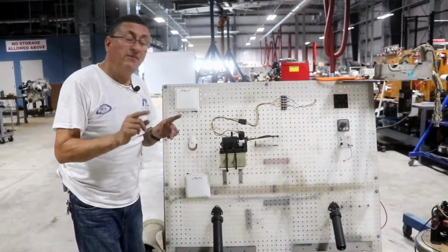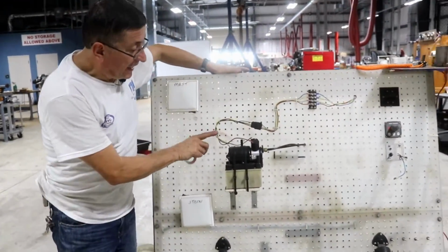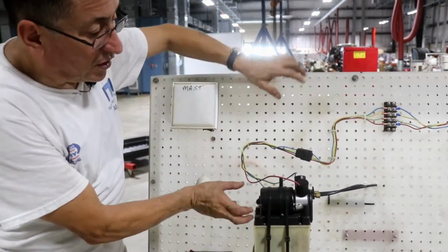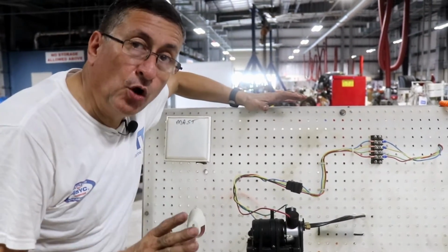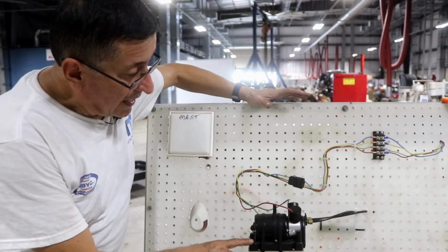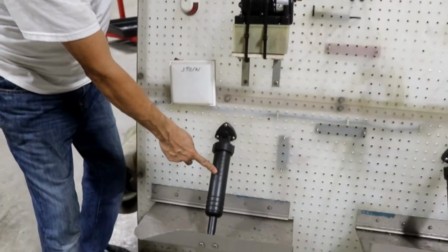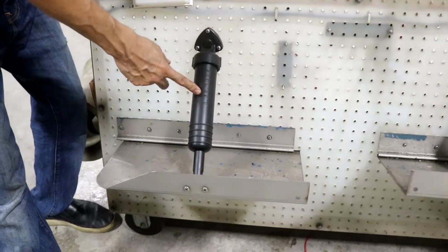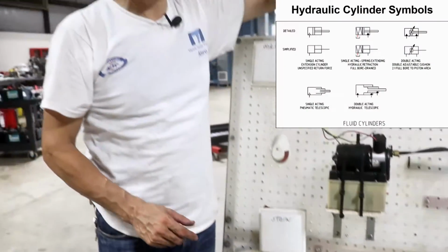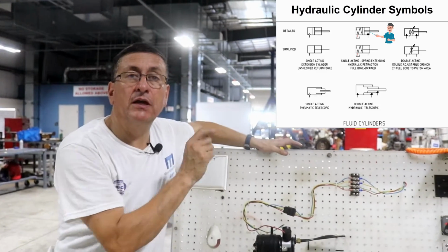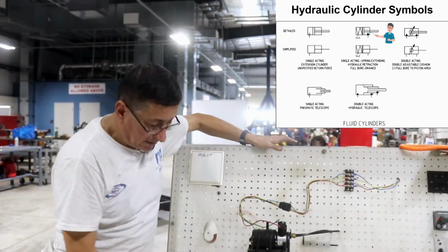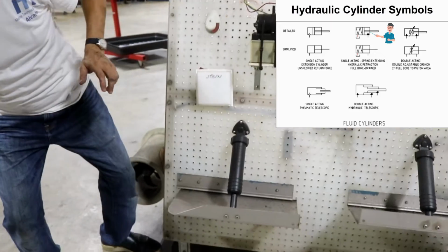There are trim tabs with flaps like this, with the electric motor, a DC reversible motor, 12 volts or 24, electro-hydraulic. And the actuator is like the actuator that we have on the screen: single port, single shaft, a spring return. This one is a spring return.